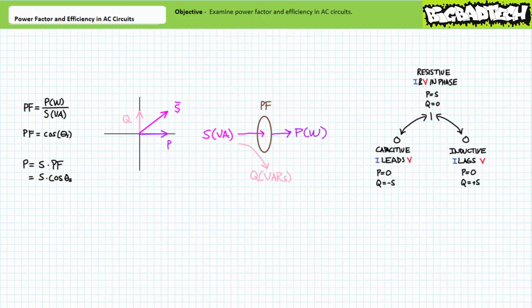Power factor is ordinarily expressed as a decimal number, although sometimes is expressed as a percentage. Additionally, power factor has a flavor, either capacitive or inductive. Capacitive occasions in which current leads voltage are sometimes referred to as having a leading power factor, whereas inductive occasions in which current lags voltage are sometimes referred to as having a lagging power factor. This being said, most real-world power factor analysis scenarios involve motors, which unless explicitly stated otherwise, are ordinarily always assumed to have a lagging power factor. This default flavor often goes unstated on a motor nameplate.